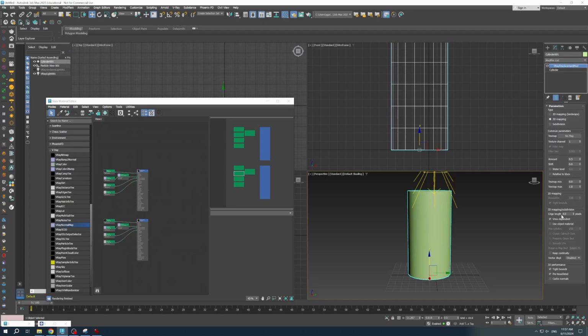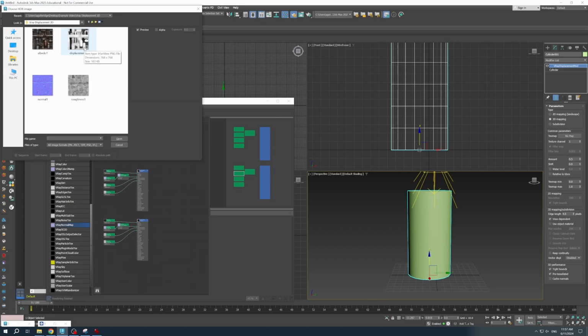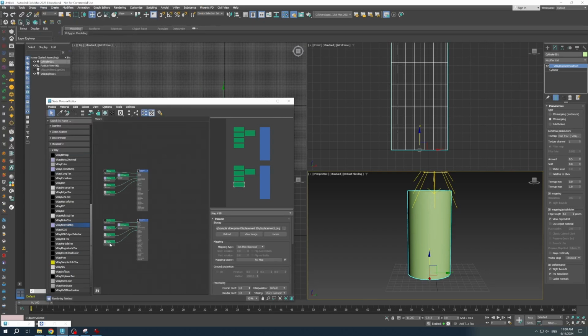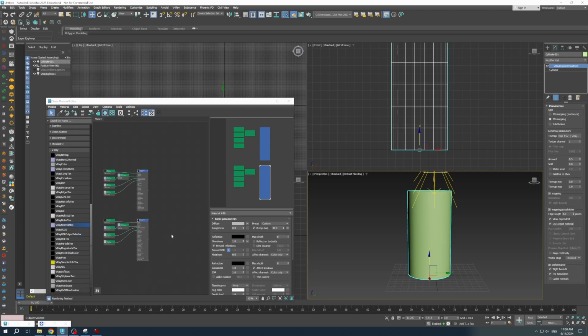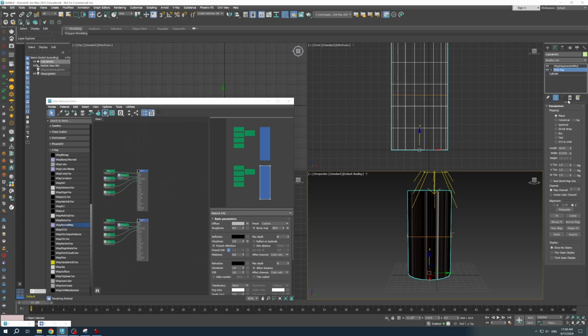No, so I start with the V-Ray displacement modifier, and just quickly apply it to the sphere. Yes, and we also need to do a UV map so that it knows where to go. I'll just use a cylindrical one, keep it simple for this.